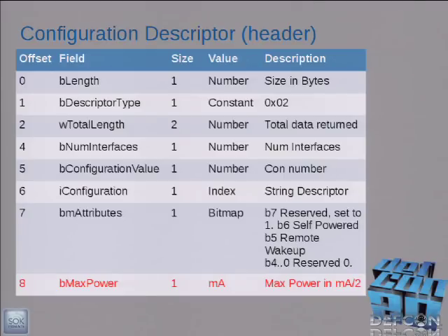So this configuration descriptor is gotten next, and again, it starts with the length, and then the type, which is type 2. They're real creative, right? 1, 2, et cetera. And it gives you some information. The last bit that it gives you is the maximum power, right?